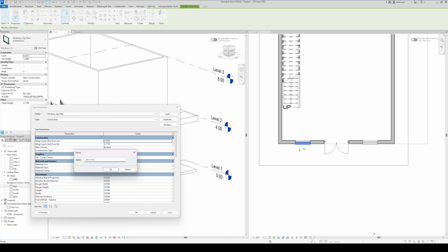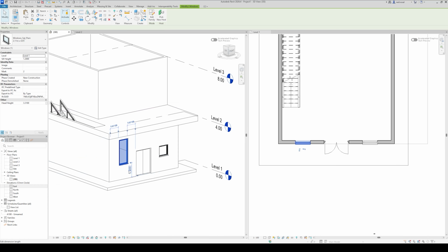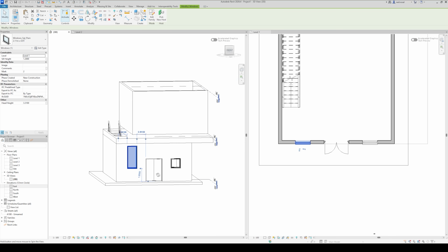I believe this door's height is 2.11 actually, so I want to align it to my door. So I'm going to go 2.11 meters, and I can fix its height, maybe 2.11 meters in the height panel, and then the width is already 0.91. I'm not going to change the width. I actually like that width.